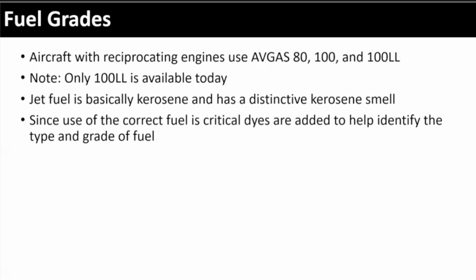Avgas 80, 100, and 100 LL. LL stands for low lead. Okay. Only 100 LL is available today. Right? Anywhere you go, what you're going to see is 100 LL. Jet fuel, you're going to smell it. You'll love the smell of jet fuel in the morning, but you're not going to see that in the aircraft you're going to be flying.